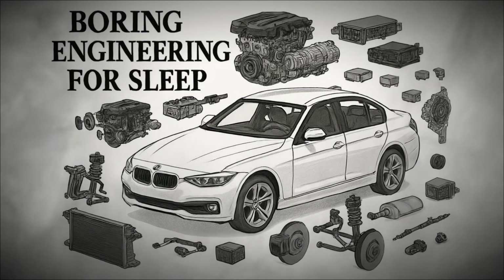Drum brakes are less efficient at cooling and more prone to fade, but they are cheaper to manufacture and can provide strong braking force at lower cost. For this reason, they are still used on the rear wheels of some small or budget cars where braking demands are lower. Regardless of whether disc or drum brakes are used, the fundamental principle is the same. Hydraulic pressure multiplies the driver's input and applies it to friction materials that slow the rotation of the wheels.